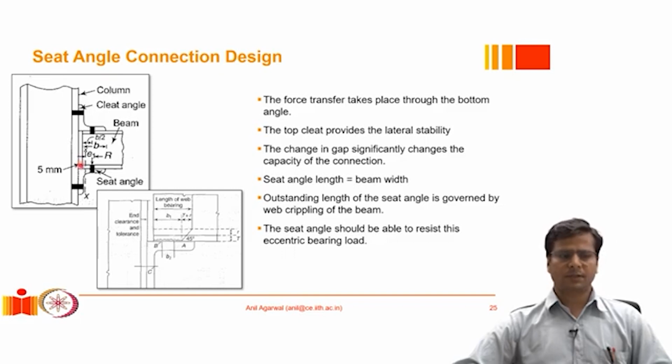However, the downside of it is that if this gap is too high, then the angle here will be loaded with a very large eccentricity. You can appreciate that if the gap between the beam and the column flange is increased, that increases the eccentricity which is acting on this angle. So if I may draw this angle,